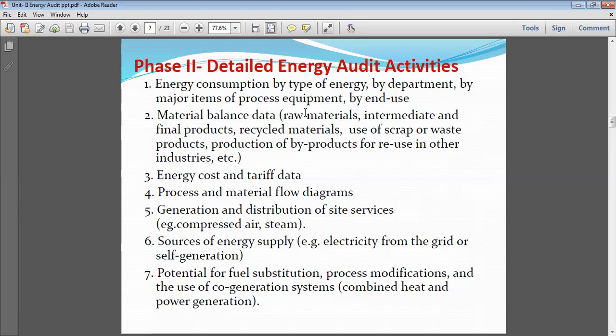So I will give my example, where we conducted an energy audit at Hindustan Lever Limited, now Unilever, in the Khamgaon factory. It is a soap factory. During that time, it was found that as per the recommendation, the temperature to be kept at 15 degree water temperature, say cooling tower cooling water. So it is 15 degree, for example, but they were using a temperature of 10 degree. So it is not needed, 10 degree.